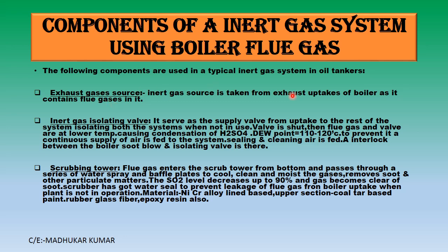Okay, so this is basically the exhaust uptake of the boiler. The inert gas isolating valve serves as a supply valve from the uptake to the rest of the IG system, and if it is closed, the IG system is isolated from the boiler. When the valve is shut, the flue gases and the valve are at lower temperature, causing the condensation of